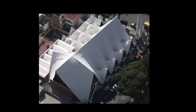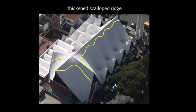From the outside, there are two what I would call interesting features. One is the scalloped ridge at the top of the shell. Here's where the concrete thickens, and it thickens not necessarily for an aesthetic reason, but really it's there for a practical reason. In his calculations, Candela determined that there would be too much tension in the shell unless there was more weight added at the top. So Candela's solution to adding more weight was to add more concrete and thickening it. But he didn't just add a slab of concrete, he created this scalloped pattern to make it more aesthetic.